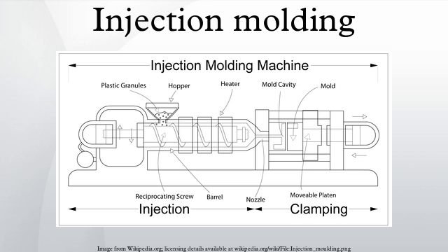Thermoplastics are prevalent due to characteristics which make them highly suitable for injection molding, such as the ease with which they may be recycled, their versatility allowing them to be used in a wide variety of applications, and their ability to soften and flow upon heating. Thermoplastics also have an element of safety over thermosets. If a thermosetting polymer is not ejected from the injection barrel in a timely manner, chemical cross-linking may occur, causing the screw and check valves to seize and potentially damaging the injection molding machine.